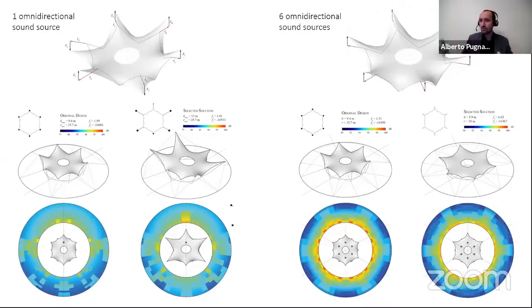The audience area for the purpose of this optimization is located outside of the perimeter of the pool. The high points of the pavilion are allowed to vary in height, and they can also be moved along the high point center axis to increase or decrease the overall covered area. We use the image source method to evaluate the acoustic response just up to the first order of reflection, and optimization was performed using a multi-objective genetic algorithm.